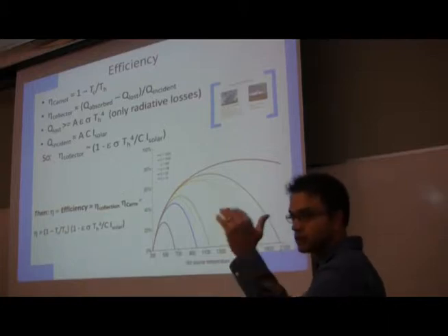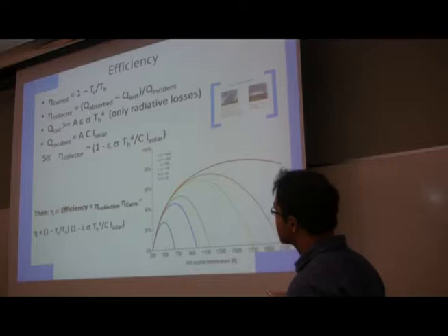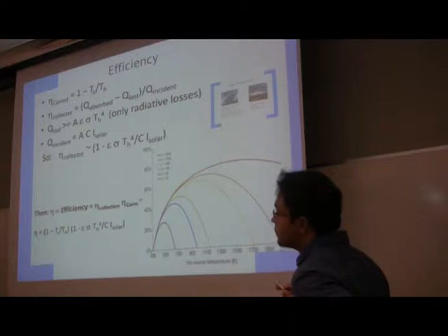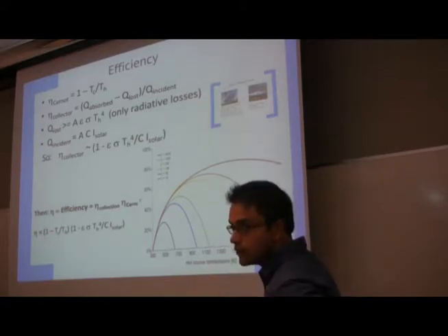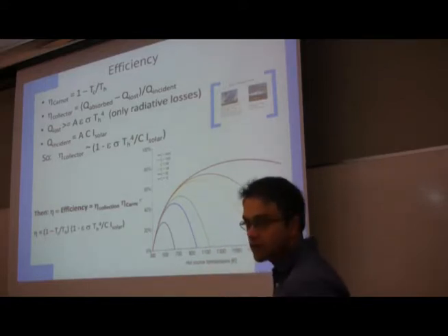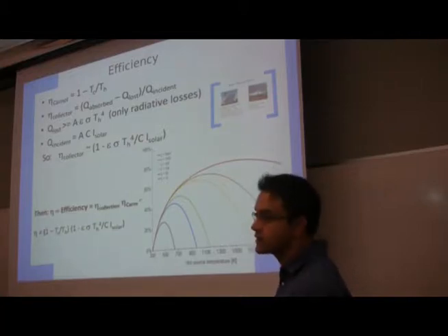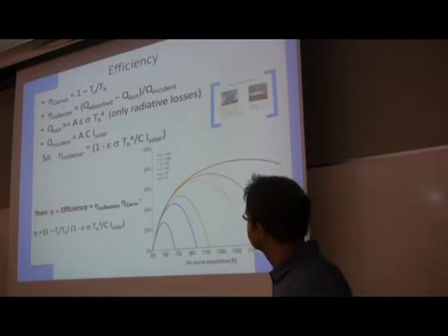This is theoretical, so you have the upper limits here. And the Carnot efficiency, as we saw before, is 1 minus Tc over Th. Collector efficiency, now we'll go into a little more detail, is defined as the heat absorbed by the collector, which, if you remember in the solar cooker's case, again, I'm just drawing an analogy, was just whatever heats up, right? Which in that case was the bottom black plate, or the cooker itself. It's whatever heats up, minus the heat loss, divided by whatever is coming in.